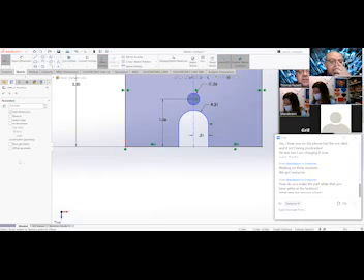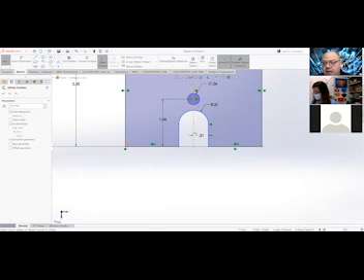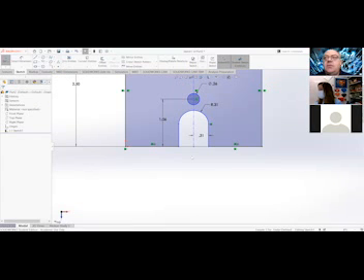It's that smart. And then we did bidirectional. When you do bidirectional and you select the center lines, they become object lines when you offset them. That's where those 2 lines came from. I accidentally deleted the 0.31 dimension when I trimmed things out. So it would be 0.31 on each side. Does that help?